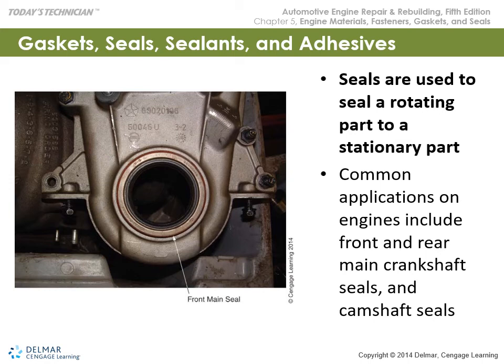Seals. Rotating parts. Now, seal technology has advanced, and seal surfaces are striated in this crankshaft situation. They have striation, so a very small amount of oil is always on that sealing surface. You don't have the type of seals today that leave a ridge into hardened material. And also in some applications in high-valued engines, there's a wear sleeve on the nose of a crank, for example, and a very wide sealing surface so that there's constant lubrication, and the actual nose of the crankshaft has a wear sleeve that is replaced.